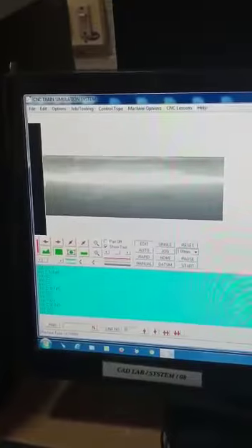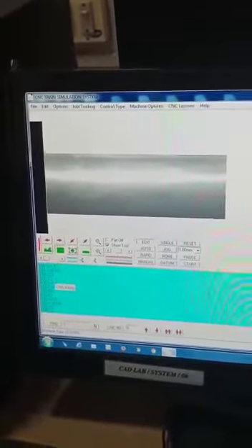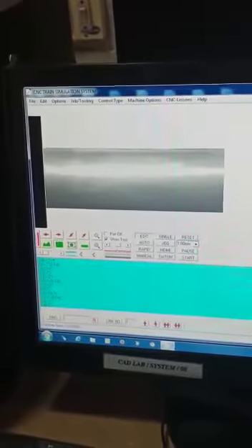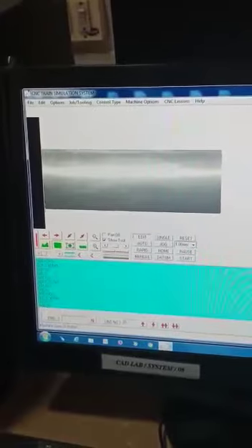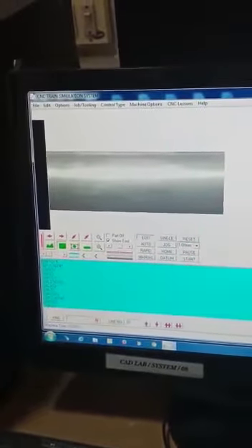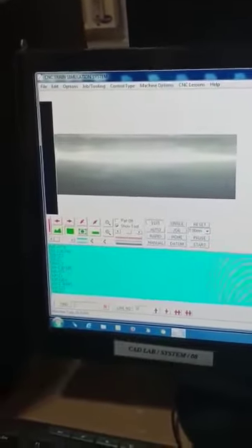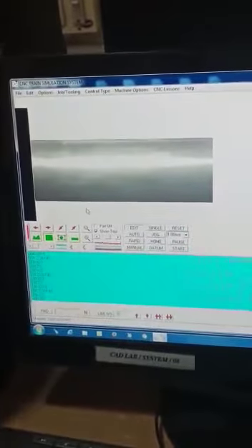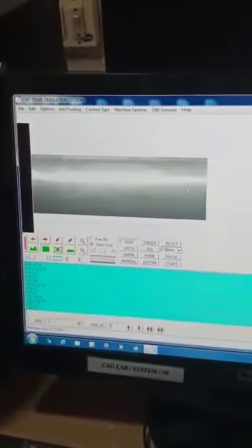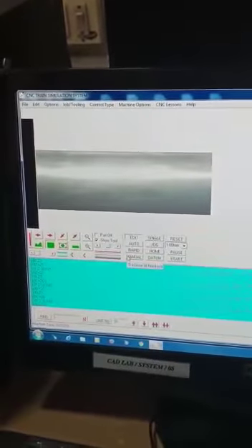That is, the tool has been sent out. So again, G00 Z3 is the reference point position. Again you have to write G00 X21. In some cases you can write G00 X21 Z3 on a single line also. Okay, G01 Z minus 30 F45. Now again the linear interpolation goes along the length from 70 to 30. So the 30 has been faced, and now G00 X20.5.